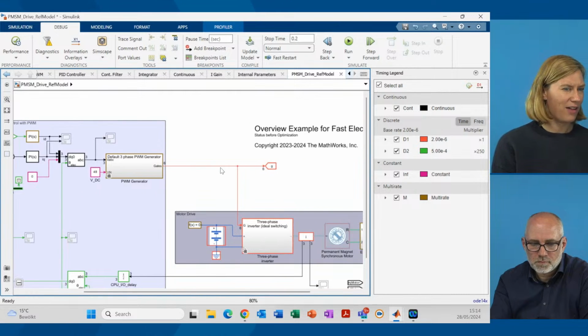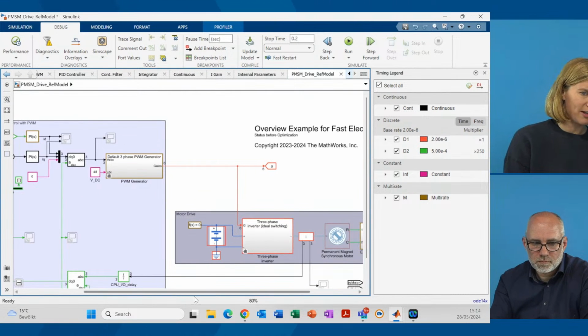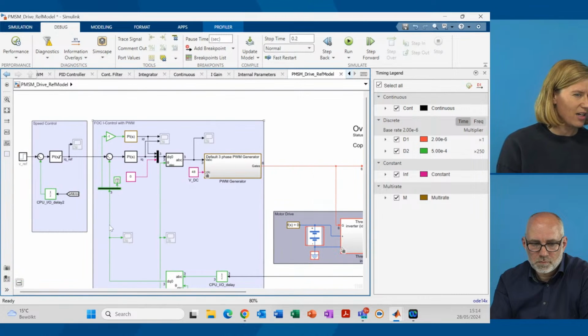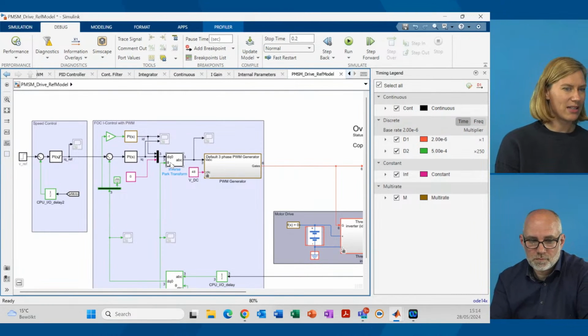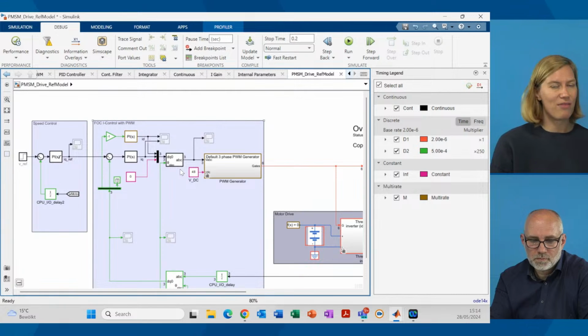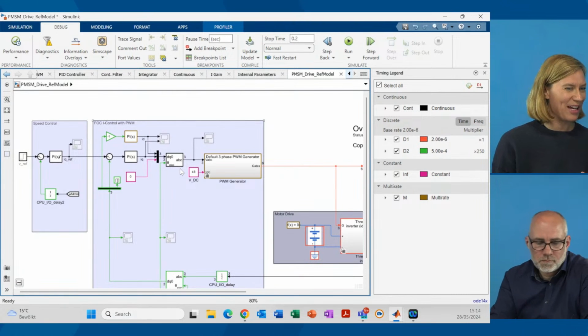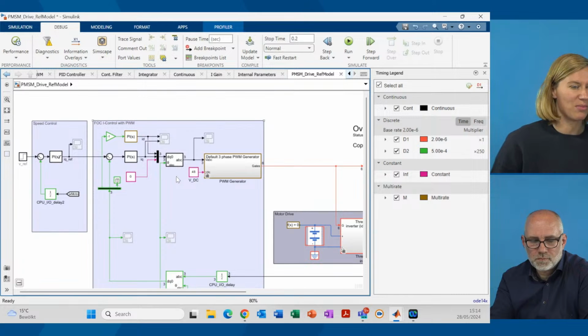Then there's 500 microseconds going on as well, highlighted in green. It looks as if this was intended for the control loop, but we can also see some black signal pointing to a continuous time signal. So probably it was intended to have the controller running in fixed step, but it didn't really happen, at least not completely. So there are still things to fix right there.